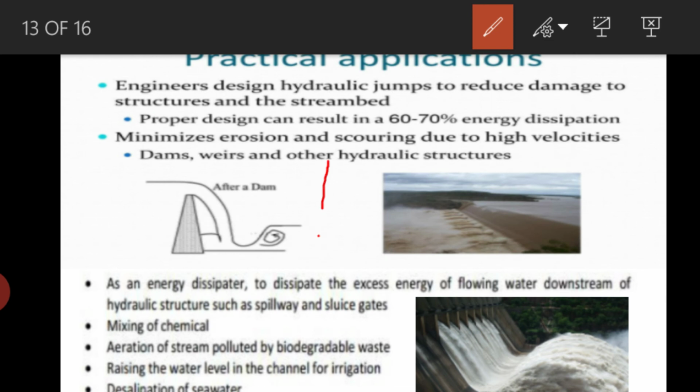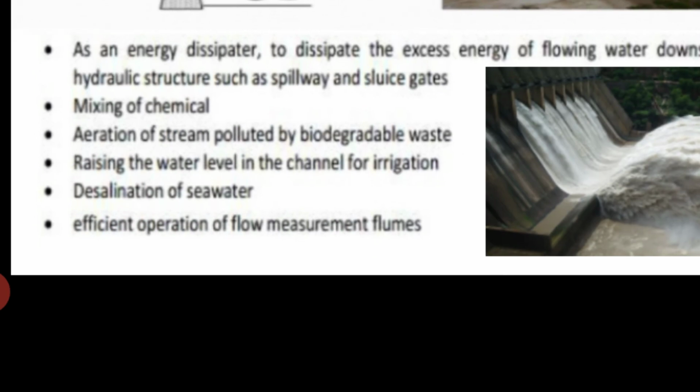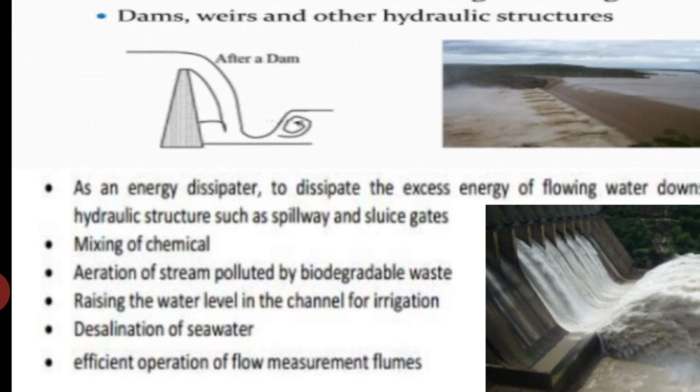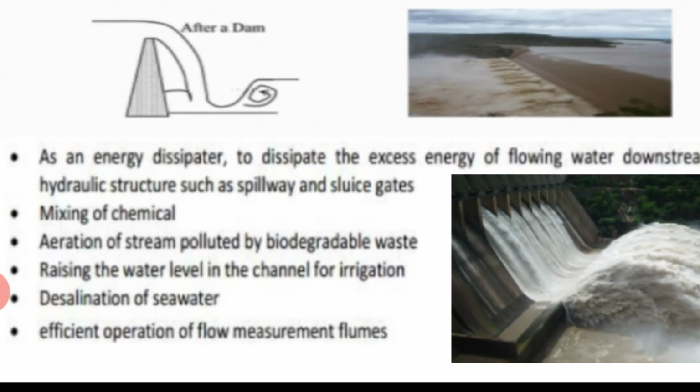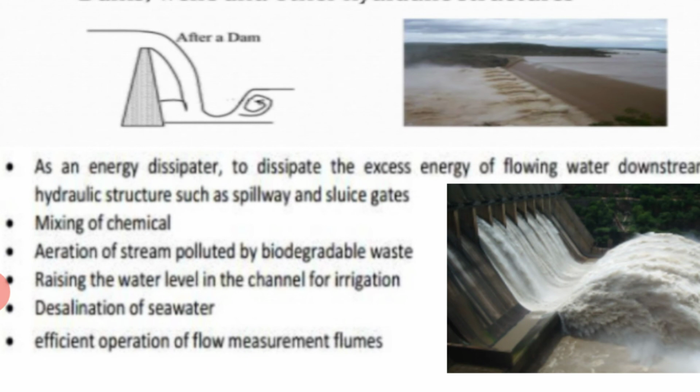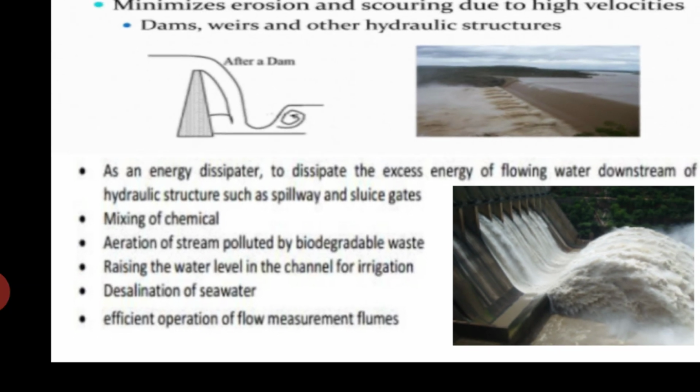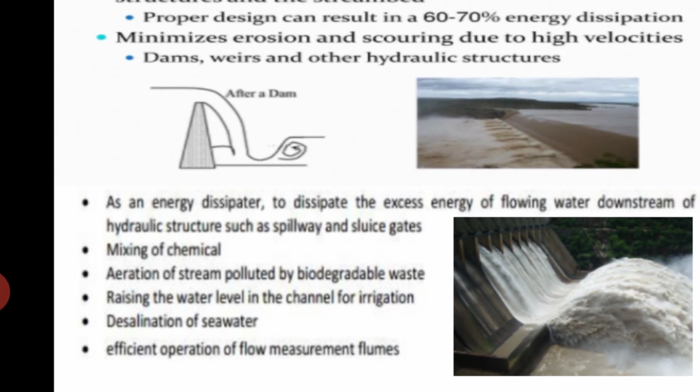So next, again, some applications. As an energy dissipator, to dissipate the excess energy of the flowing water downstream of hydraulic structures such as a spillway and sluice gates, the hydraulic jump can be created.